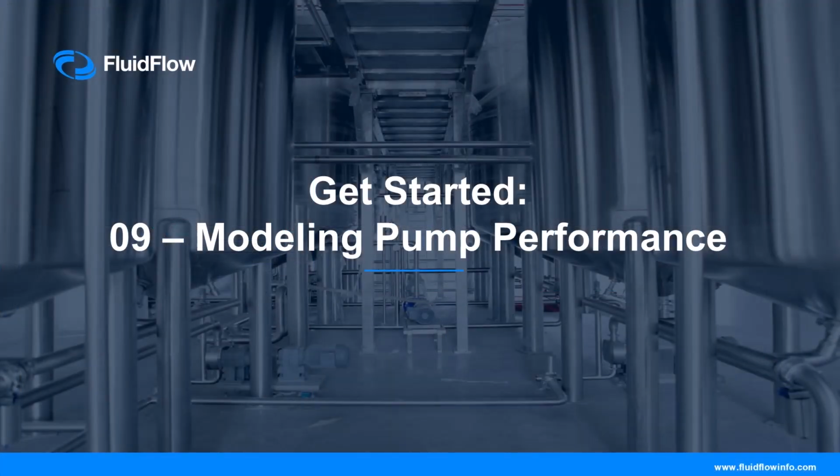Once the duty point or range is determined, you can replace the auto-sized pump with a pump model from the default database or add a specific pump model to the database for evaluation. This will allow you to assess the suitability of proposed pumps within the system.